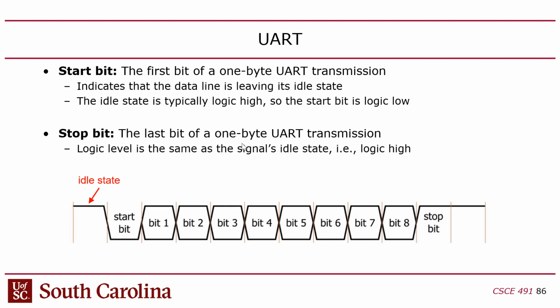So UART is a really simple protocol because it's designed to be slow. It's designed to be no faster than you can type. It's designed to run at typing speed because it's a textual protocol. The way it works is there's one bit that flows in each direction, and that bit idles at 1 all the time. So the idle state is active high, logic 1.